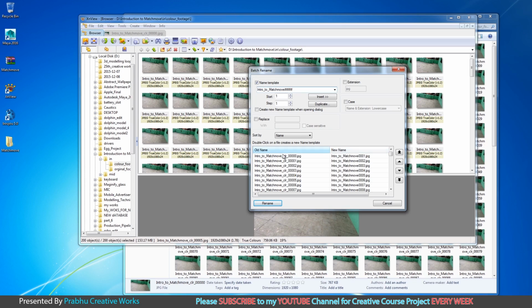So in the old name, see here it starts from 000 and ends with 0019 over here. But in the new footage, here you will set the start value to 1, so that means it will start with 0001 and end up with 200. So this is what we want. In After Effects we cannot set it like this, which is why we use XnView to set the start and end value. So here, extension, I will leave it as it is.